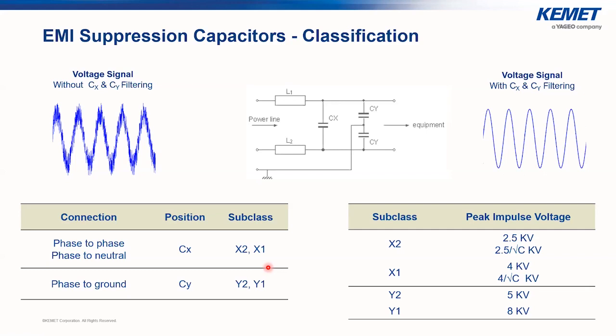So generally, we have international certification and standard that we follow, and we define these capacitors following these functions or characteristics. Mainly, if the capacitor is connected between phase to phase or phase to neutral, in this case, we will be talking about differential mode capacitors or X capacitors. And if the capacitor is connected from phase to ground, in this case, we will be talking about common mode capacitors or Y capacitors.